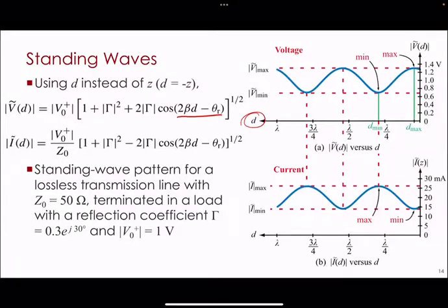That is theta R. So theta R, 30 degrees. So don't neglect your theta R. You can see why the magnitude is usually the most important thing, right? Because that's telling you how much gets reflected. That's the thing you're often predominantly interested in, which is why theta R can sometimes get thrown under the bus and forgotten about, okay? Okay, this 0.3 e to the j30 is that. So let's see if we can convince ourselves how it's that.